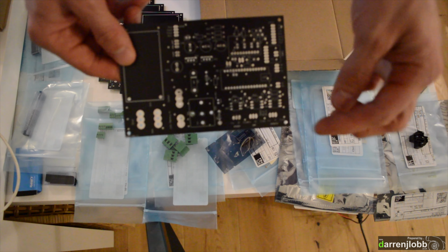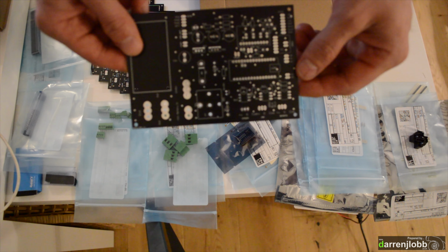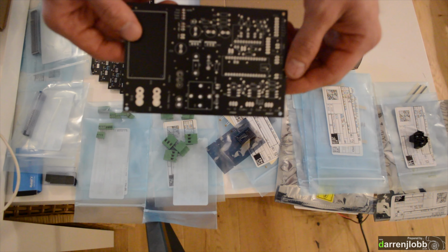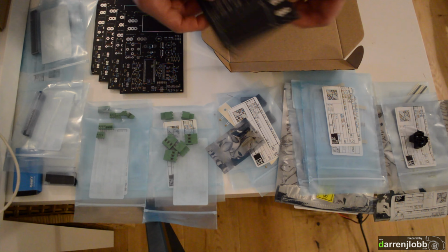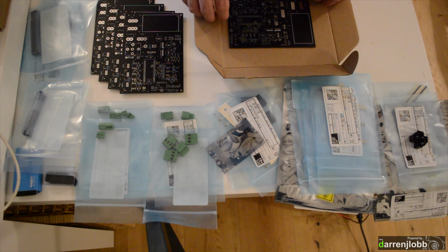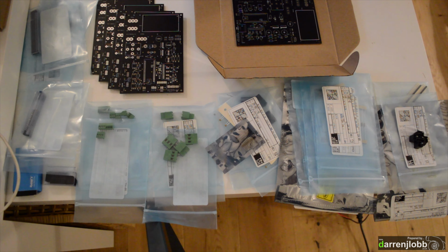I'm kind of the wrong side of the camera here. Each individual component, generally, unless it's really obvious, is labelled. All the resistors and the capacitors are labelled R or C and then a number. These correlate to the numbers that you'll see in that text file in the PCB directory. So if you're not quite sure what value resistor or capacitor goes there, look at the file and they'll match up. So that's pretty impossible to get wrong. There's a couple of diodes as well. They're also labelled D1, 2, 3, 4, etc. Again, labelled in that folder.